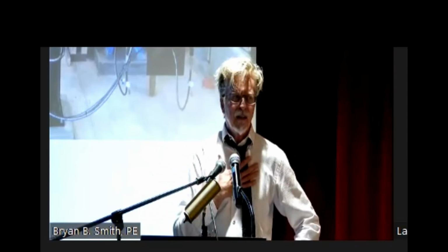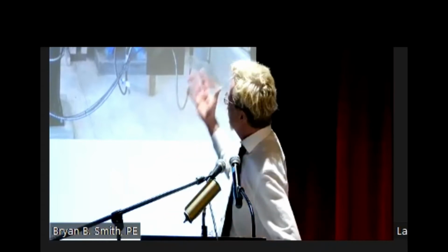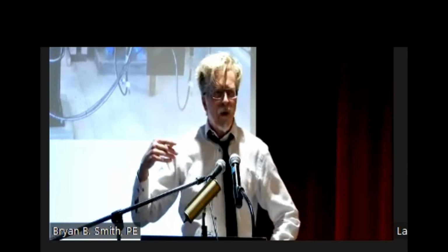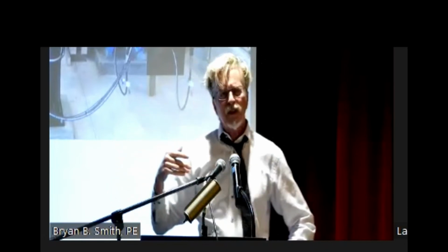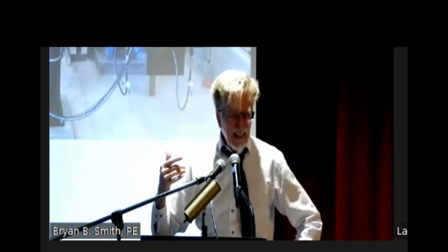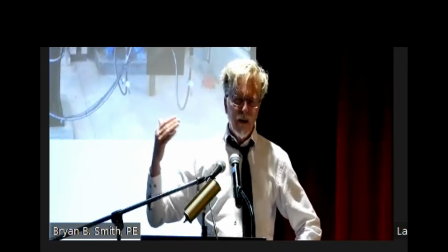So we're here today to protect our pumps. So we look at a device like in this picture where I can manipulate the pump from a starting and stopping standpoint. Now, wastewater pump stations, I want to start at 100% and then ramp it back down if I have variable frequency drives. It's great because I need some flushing action. I'm like, give me some flow velocity. Let's get this going. And then ramp back down.